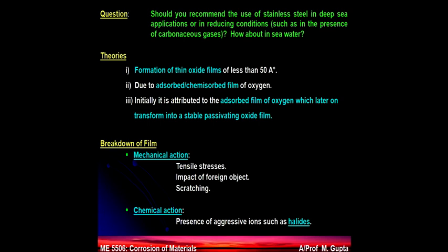Seawater contains 3.5% sodium chloride. Chlorine can damage the protective oxide layer. If the area is damaged, there is no oxygen to repair it. So that area is equivalent to active stainless steel if you look at your galvanic series.